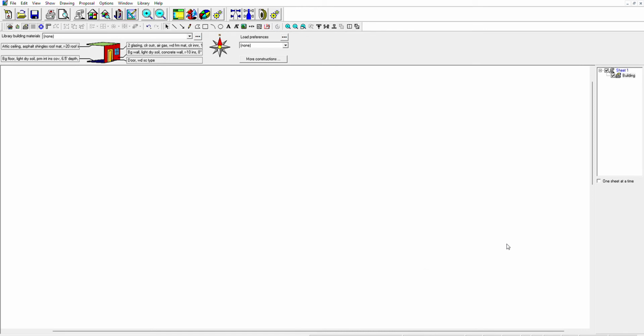So step number 1, you have your HVAC. See, I don't understand why I cannot do this. It says HVAC Shapes Toolbox. So we have this in here, all good. Now we go to the grids. We go to Drawings, Grid Settings. We have 6, 6, 6, 6, all 6. Okay, grids and snap, all good then.